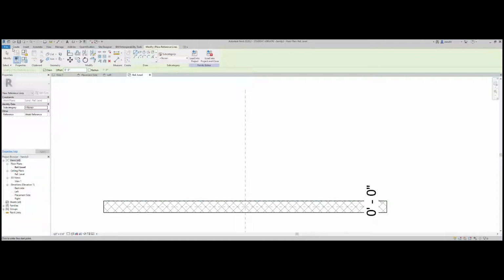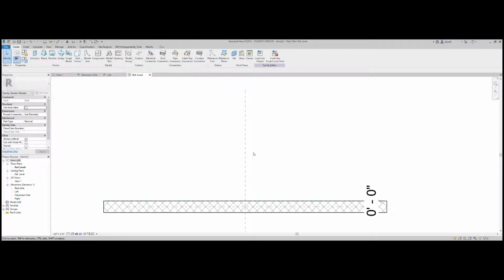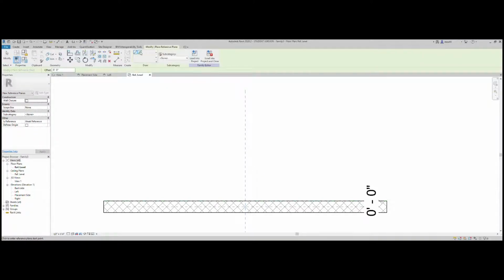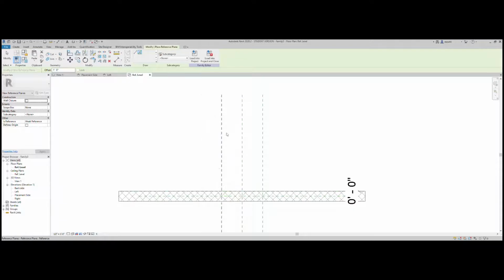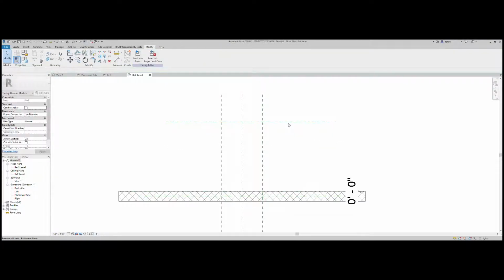Let's add in some reference lines to give them dimensions and add some parameters. So I'm gonna create similar CS, pick line, give it any number, 1 feet, this way, offset this way. We can also create some reference lines going this way to give it a depth.